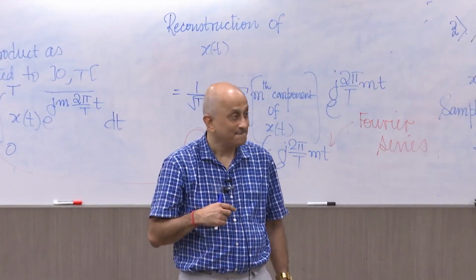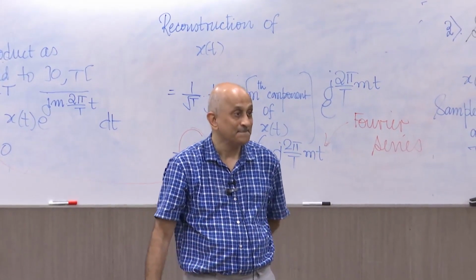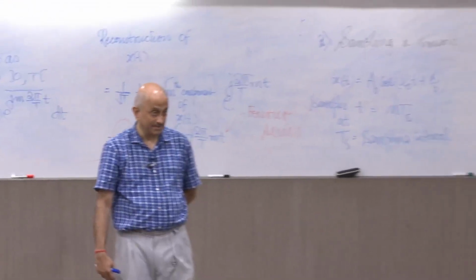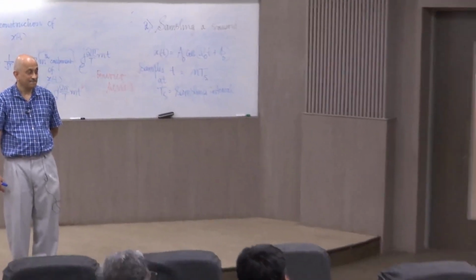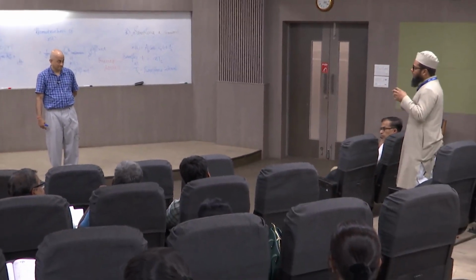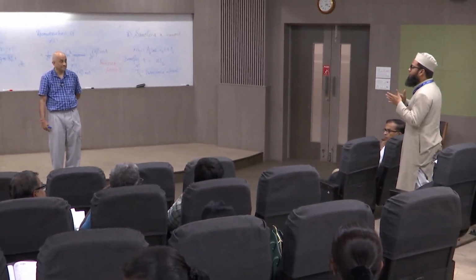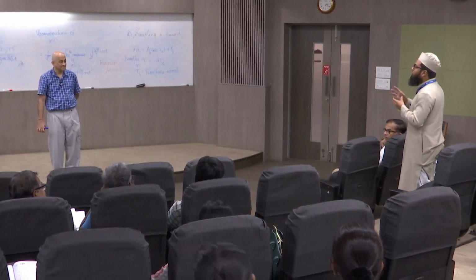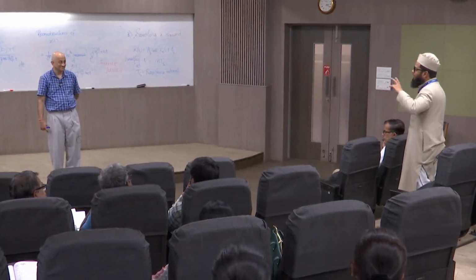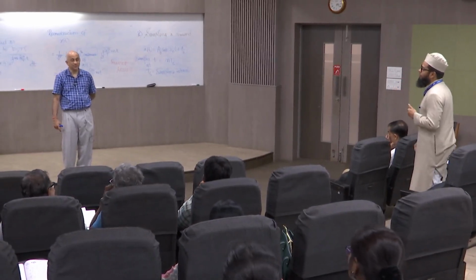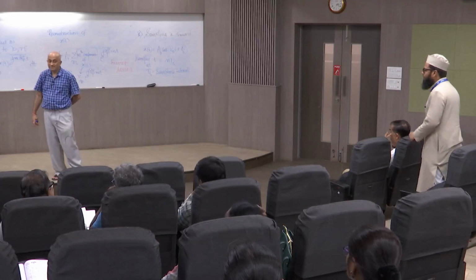To reconstruct it, the sampling frequency should be double. Okay, that's true. But we have also thought of it in terms of a combination of sine waves, where signals have multiple sine wave components. Then we find the maximum frequency there, and the sampling should be double that maximum frequency. True, quite true.